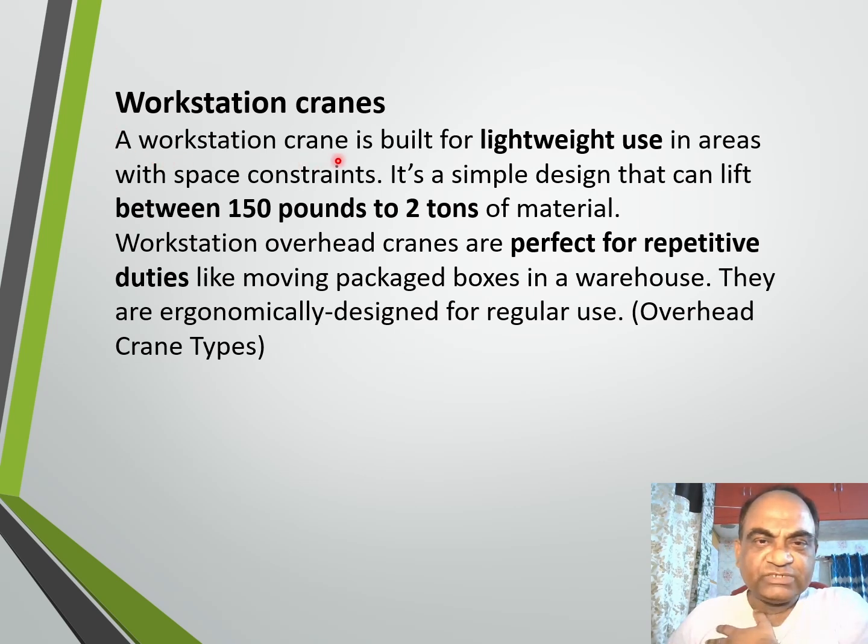Workstation crane: a workstation crane is built for lightweight use in areas with space constraints, and it has a simple design that can lift between 150 pounds to 2 tons of material. Workstation overhead cranes are perfect for repetitive duties like moving packaged boxes in the warehouse. They are ergonomically designed for regular use, as against the overhead cranes that are made for higher capacity, not for smaller capacity. So in the warehouses, workstation cranes are expected.